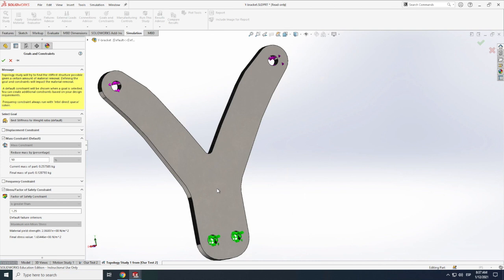That we can say, I want this piece. This piece would normally break. Actually, I believe it's the other way around, because this piece would normally break at the yield stress, which, for instance, for steel, we already know is around 200 megapascals. However, I want this piece to be operating at half of that, at 100 megapascals, which means that we have a factor of safety of 2 in that case,